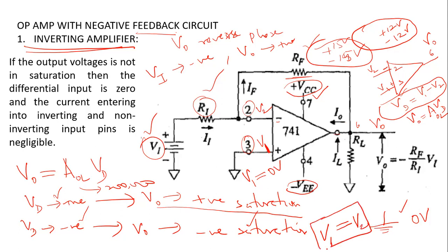Okay, so in this closed loop configuration, when you have a feedback circuit to the inverting input, the voltages at pin number 2 and pin number 3, denoted as V1 and V2, are almost instantaneously set to be equal. V1 and V2 are equal in very small fractional seconds.